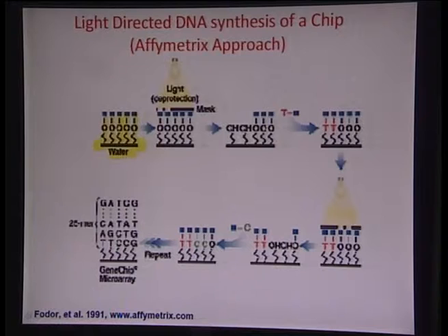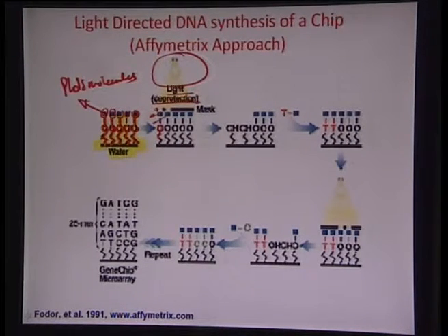One is that these blue dots here, as you see, are photomolecules, and they are capped over this linker layer, which essentially bonds the photomolecule to the substrate. In this approach, the first step is that some of these capping layers are removed, uncapped, and the way you do it is by exposure to light.